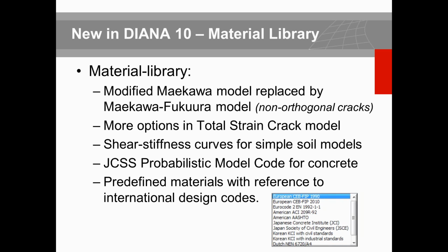We have enhanced and updated many features for tension behavior, shear behavior, and compressive behavior of the total strain crack model. We introduced new definitions for soil models to be able to capture the effect of cyclic load, taking that effect into account.